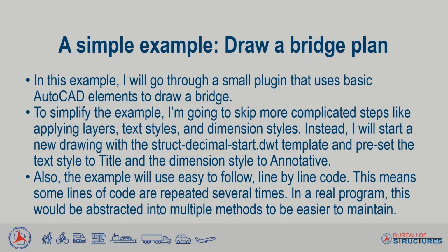Next, we'll go through a simple example where we'll develop a tool to draw a bridge plan. This example will use basic AutoCAD elements to draw a bridge. To simplify the example, I'm going to skip more complicated steps like applying layers, text styles, and dimension styles. Instead, I'll start a new drawing with the start.dwt template and preset the text style to title and the dimension style to annotative.